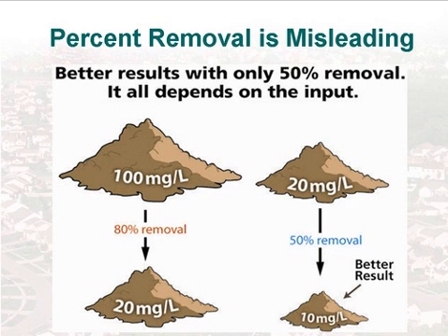reflected with percent removal. And one of the earliest cases that brought this to my attention was when we were monitoring BMPs in series. We were going from swales to extended dry ponds to a wetland. And, of course, as you worked your way down in the system, it appeared that by the time you got down to the wetland it wasn't performing at all well, because BMP efficiency in that case was being expressed as percent removal. We find as design engineers that when we have effluent data that are statistically presented, such that, for example, we know the 75th percentile performing wetland has a TSS concentration of such and such, that enables us to make better risk-based design decisions for our clients.